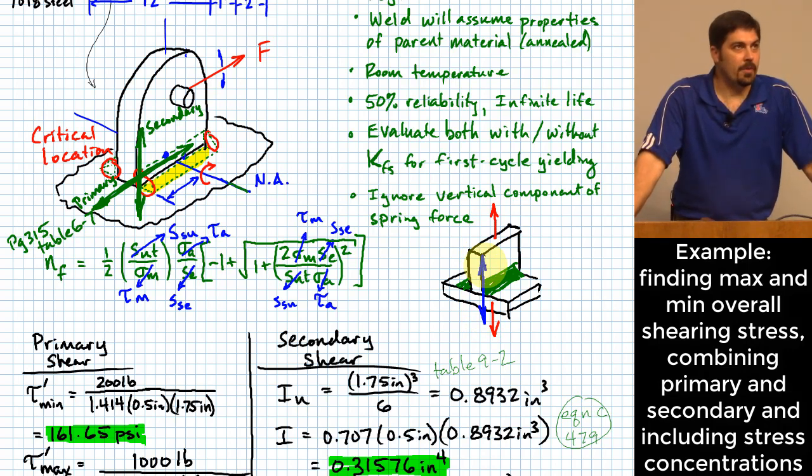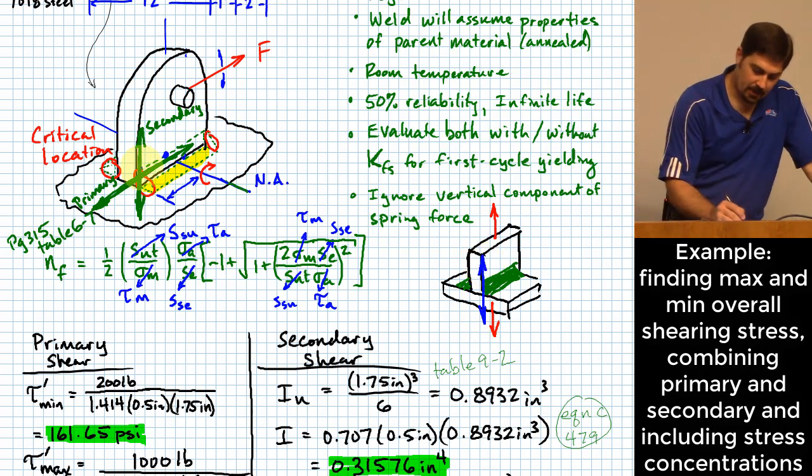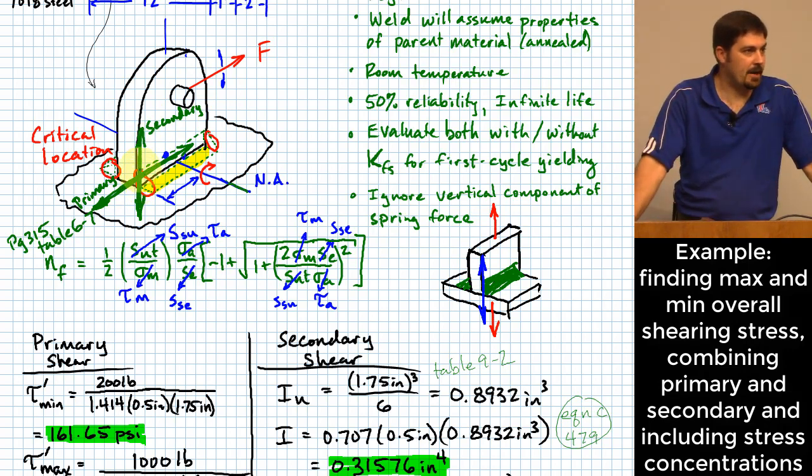Okay. Well, that's the same direction of stress that we have due to the secondary effect that's going on over here on this tab. And so this is my justification for why, if it was me working this problem, I would say the closest situation from the information given in this table is something similar to a T-butt joint. And so I'm going to select the 2.0 for my K sub Fs.